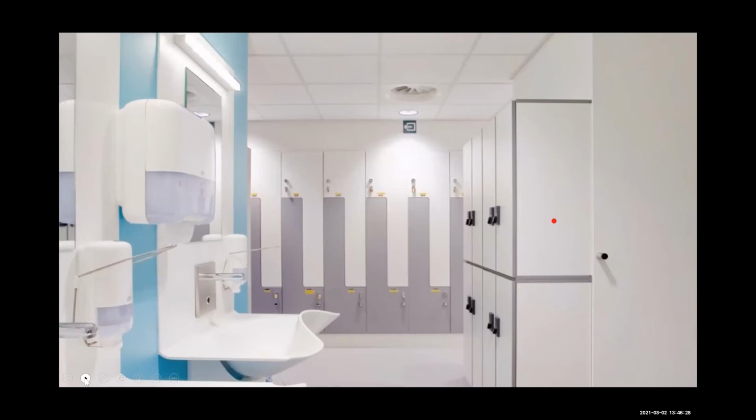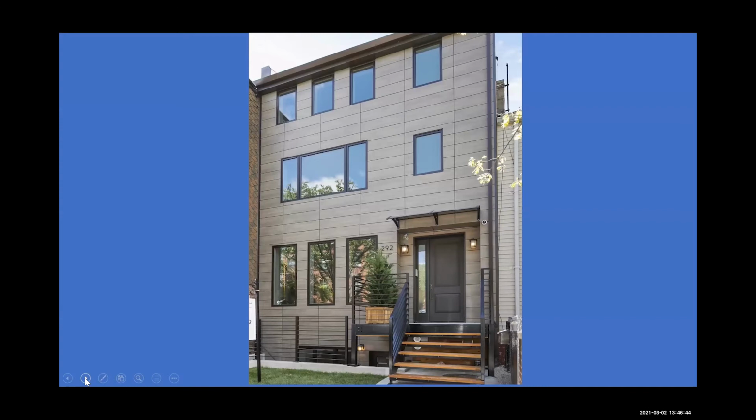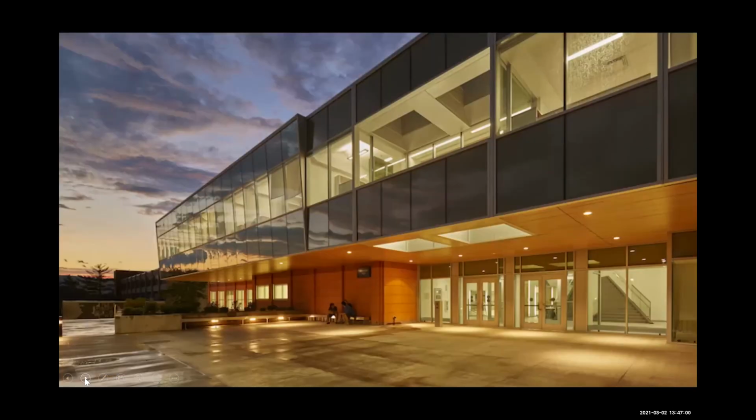And then we have toilet partitions done in solid phenolic. This is the Dale Youth Boxing Club in London. And then finally, when you add a UV protection and you use 8 mil or 10 mil thick HPL panels, they can be used exterior as a rain screen facade system. This is a residential project in Brooklyn, New York. And then another one, the last one, this is also an exterior grade phenolic project in New Platts in upstate New York.